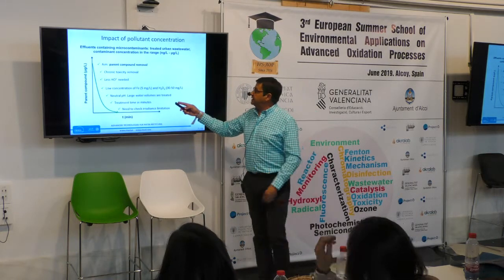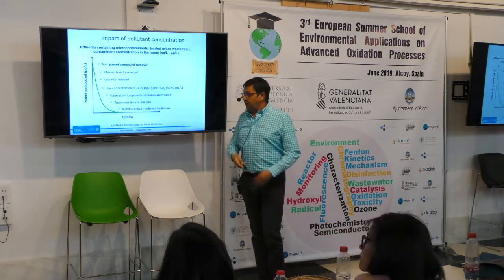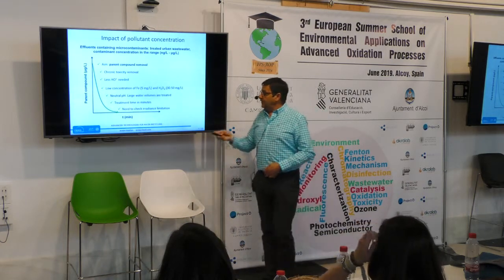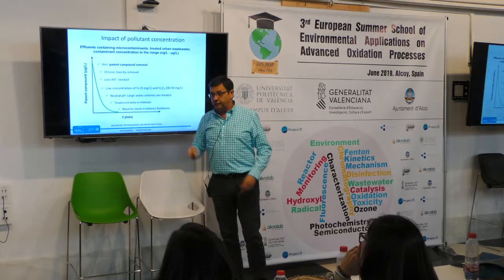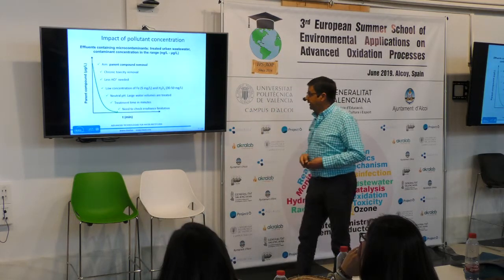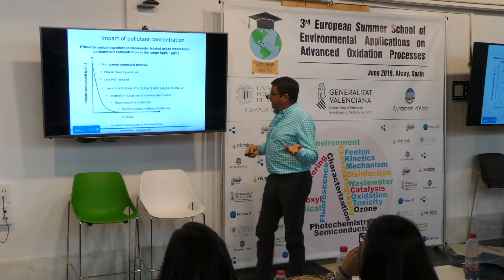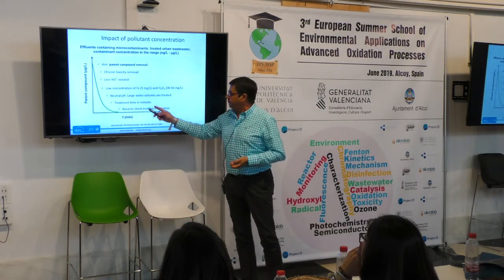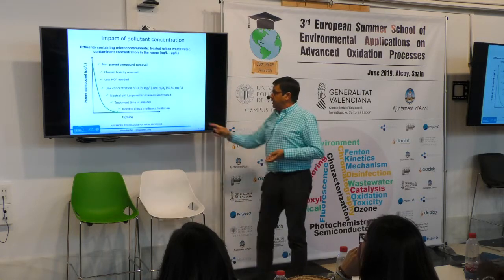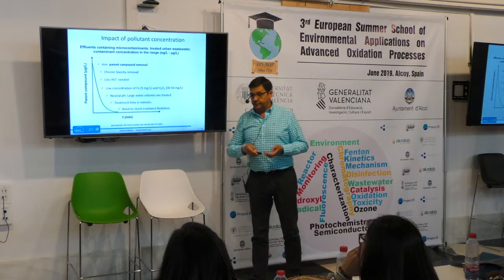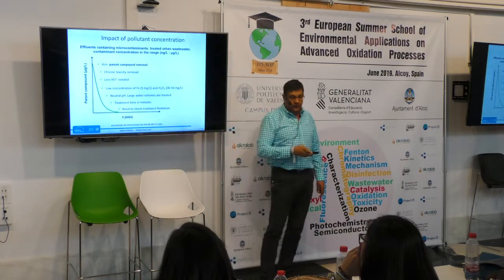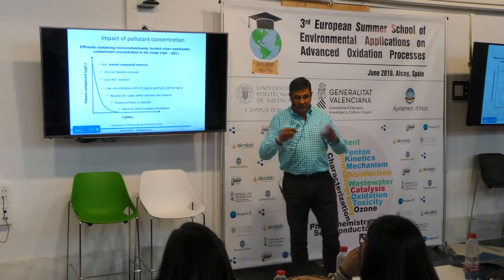In this case, urban wastewater, we want to treat large volume of water, and we need to work at neutral pH to avoid the cost of pH conditioning. Normally, in this case, the treatment time is measured in minutes, and because we use low concentration of the light absorbing species, we need to check if we work under irradiance limitation or an excess of light.